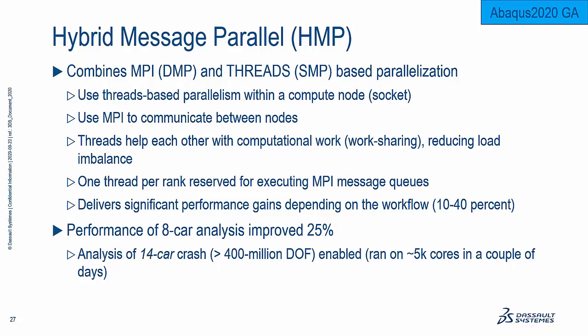And then shared memory parallel tends to be extremely fast and scale extremely well, but does not transfer well for cross connects between multiple nodes. That is what we use distributed memory parallel or message passing interface for. Combining these two can get you anywhere from a 10 to 40% improvement in performance, but the key here is